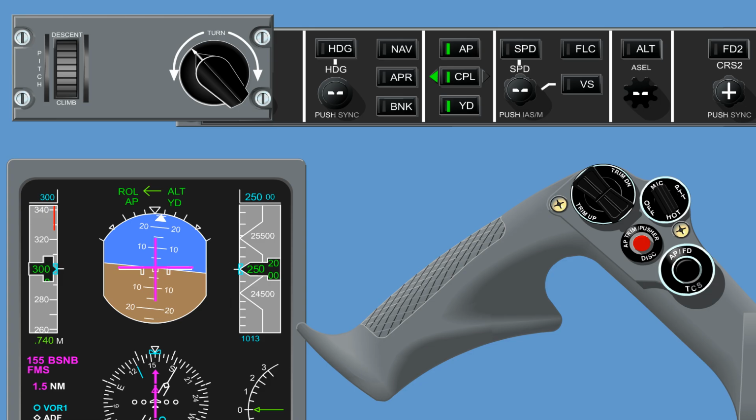The roll-hold submode is entered from the heading hold mode, with the autopilot engaged, by using the touch control steering button to manually fly the airplane to a bank angle greater than 6 degrees. The system will maintain the bank angle at the time the touch control steering button is released.